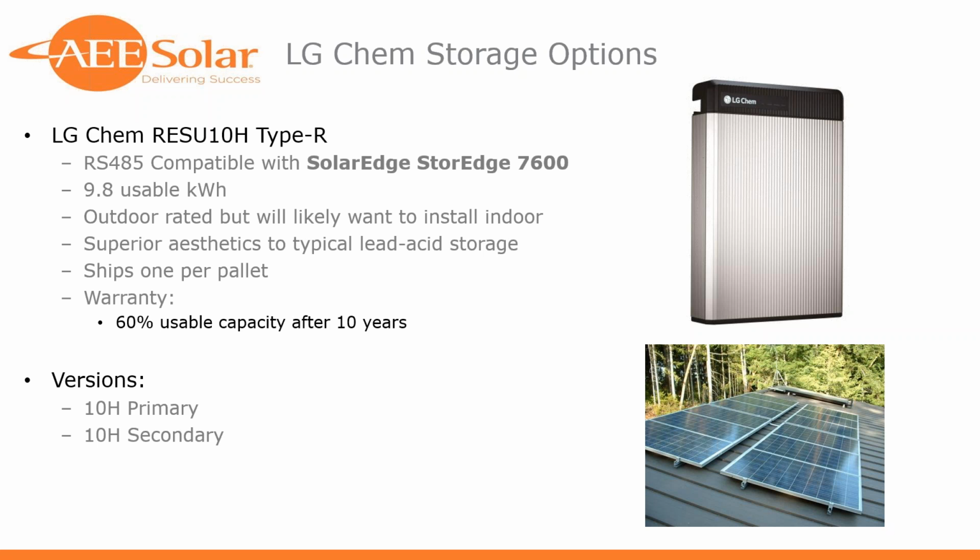Got some slides here on our most popular lithium-ion product right now, which is LG Chem. And there's a couple different flavors here. The 10H Type R, up until now, there's been no reason to refer to it as Type R because it's been the only Resi 10H on the market. The Type R standing for RS485. That's the communication protocol between the LG Chem Resi 10H and the solar+storage inverter. I talked a little earlier about making sure that you've got a good quality interface between the battery and the inverter, so that the inverter can make smart decisions on what to do with that energy: charge, discharge, idle, etc.